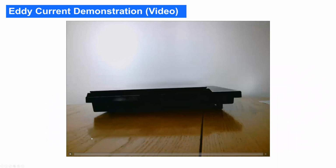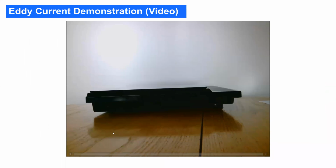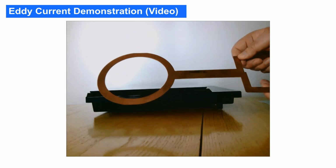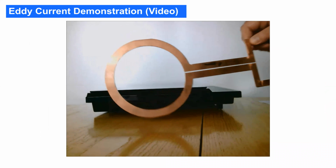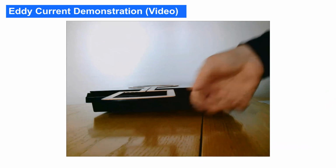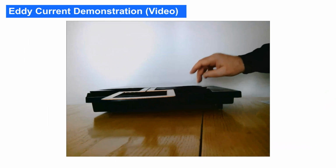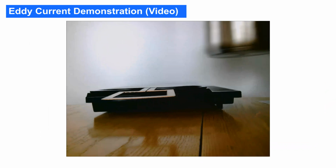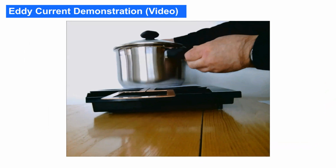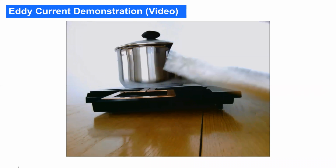To show the effect, I made a video using an induction stove. The induction stove works at about 22 kilohertz, which is quite a low AC frequency, but it's still pretty indicative of what's going on. I have a loop where I pick up the main current from the induction stove while it operates. I put a water pot, isolated, on it, and if I switch it on, I get about 100 amps AC current in that rectangular loop.